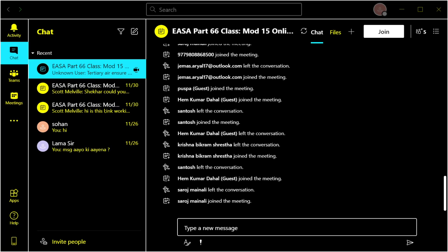Roller bearings, I'm sure you've come across these plenty of times, may be divided into 3 main groups according to whether they have cylindrical, spherical, or tapered rollers. There's a classic tapered roller. Again, if you've worked on cars, you've probably come across these in the rear wheel axle, packing the grease. Cylindrical ones are sort of smaller ones as well. We call these needle bearings. And the tapered ones can be used for thrust loads on the axis as well.